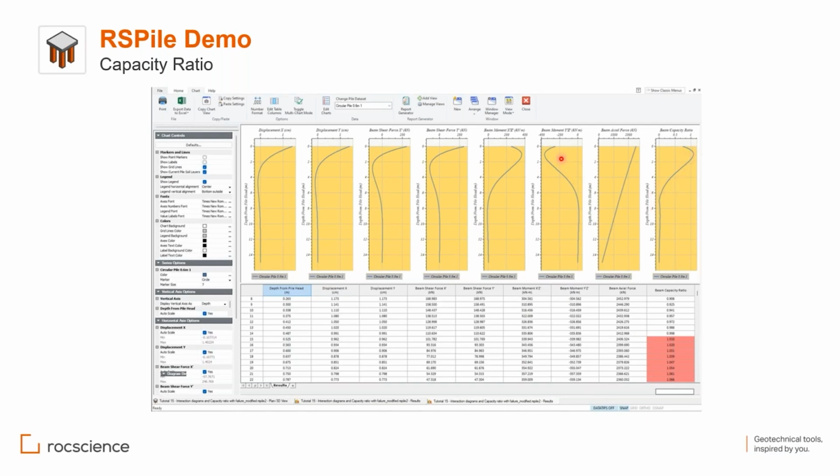When the moment is increasing, see, the moment is increasing, then the capacity ratio at the maximum moment, not by chance, of course, I made this example to show you how the capacity ratio, when it exceeds 1, you will see the red cells in the table. See, the red cells are exceeding 1. So you know your section is not adequate, and you need to increase your reinforcement or change the section diameters or increase the concrete strength so that you will have a better interaction diagram.